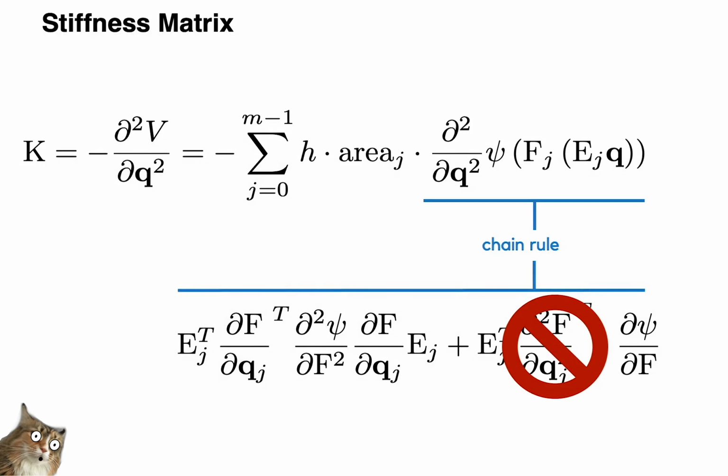For our particular cloth simulation model, we can build a pretty good approximate Hessian by just dropping this second term. This second term is related to the bending stiffness of the cloth, and, at least in what we've discussed so far, we've assumed the cloth has no resistance to bending. That means we don't need to implicitly integrate this portion of the force, and we can safely ignore this contribution to the Hessian. An important note: ignore this term at your own peril if you introduce bending to your cloth